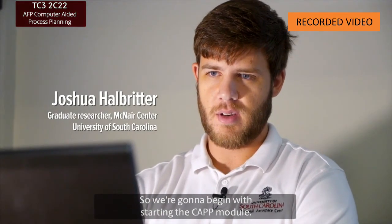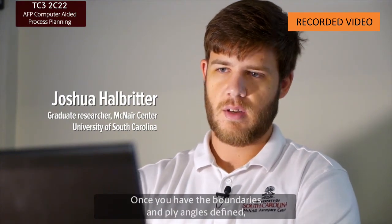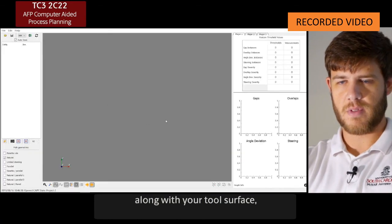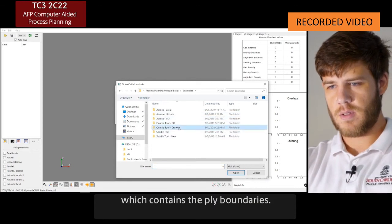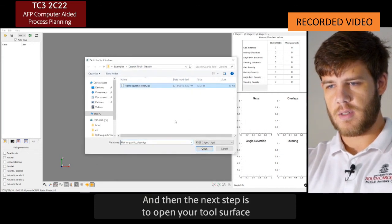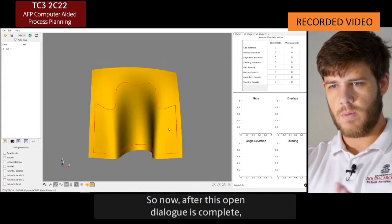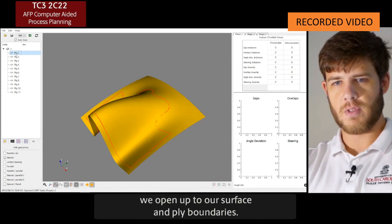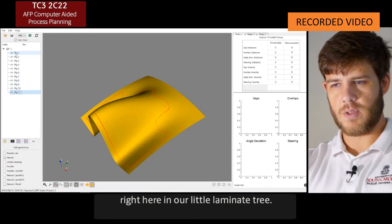So we're going to begin with starting the CAT module. So this will be the starting point once you have the boundaries and triangles defined along with your tool surface. The first thing you're going to do is open the CATIA laminate, which contains the ply boundaries. I'll go through and open that here. And then the next step is to open your tool surface that you're going to be using. So now, after this open dialog is complete, we open up to our surface and ply boundaries, and we can go through and look through them right here in our little laminate tree.